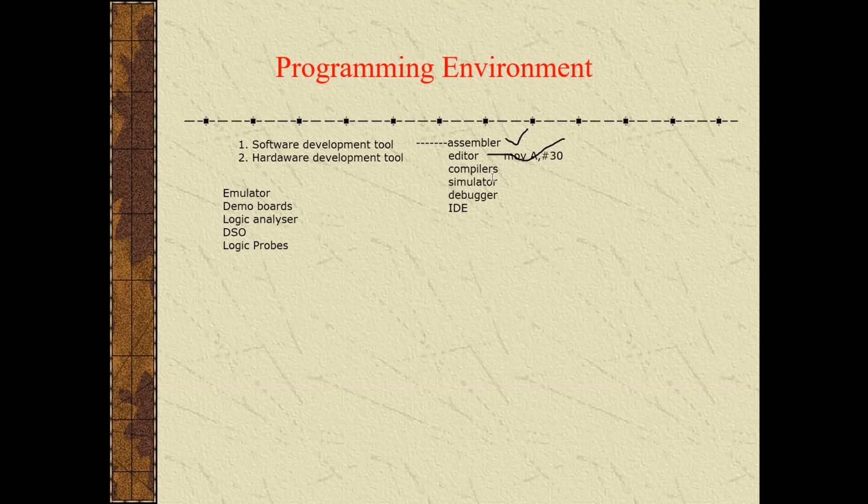The object file is given one extension, whereas the assembler list file is given another extension. The object file contains the binary code of the program instructions and information about the address of the instructions. The list file contains the assembly language statements, the binary codes for each instruction and the offset of each instruction.